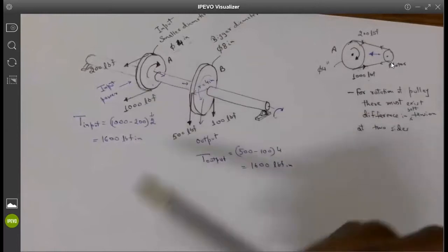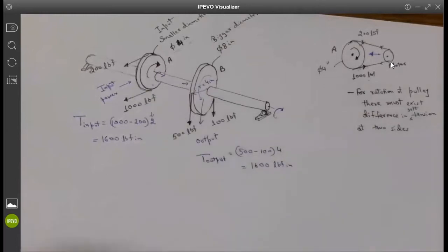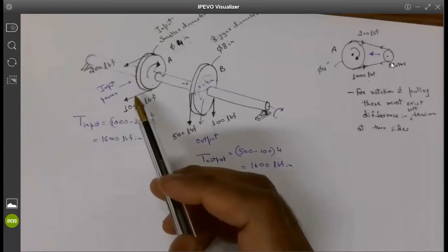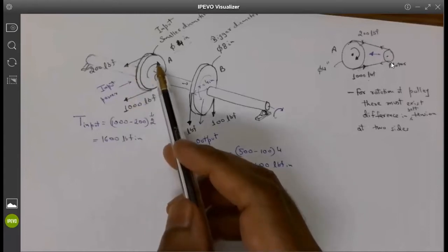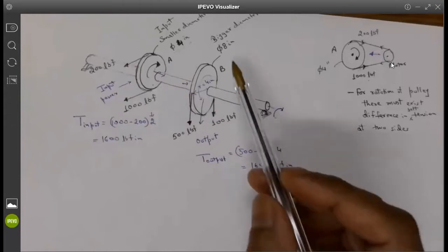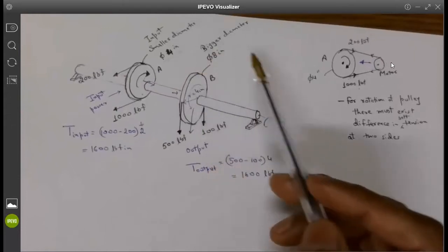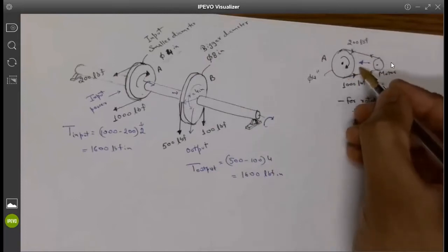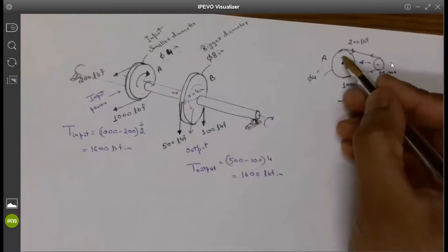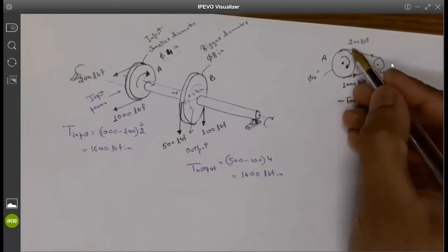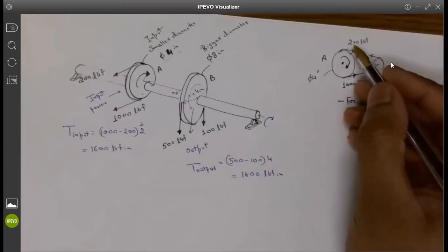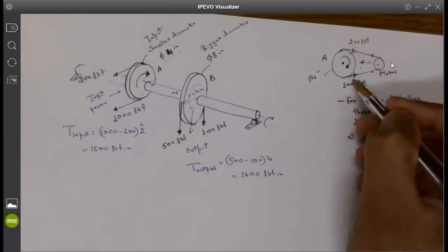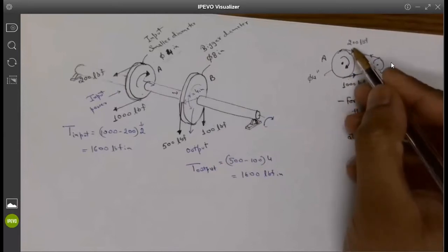But the shaft is rotating in the clockwise direction. Does it make sense? Professor, I have a question. Your arrow on the top right pulley system, the very right one. Why do you have that arrow spinning in a clockwise direction? So basically I have loose side tension on the top and tight side tension on the bottom. So the tighter side of the belt is at the bottom and the loose side is at the top.